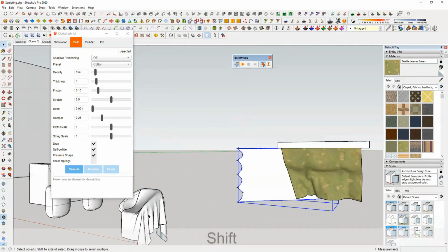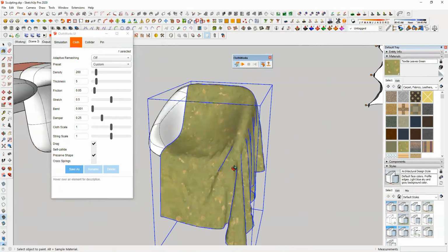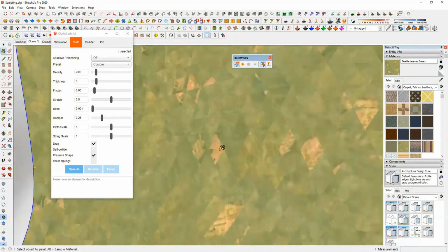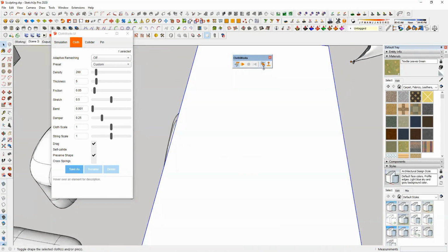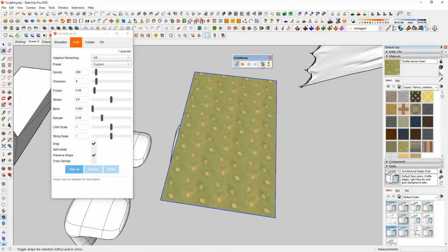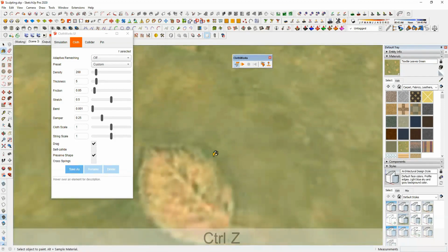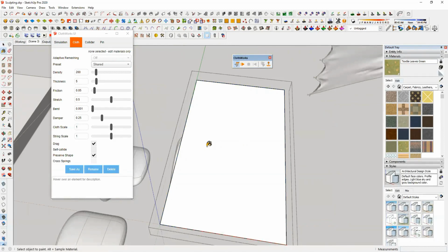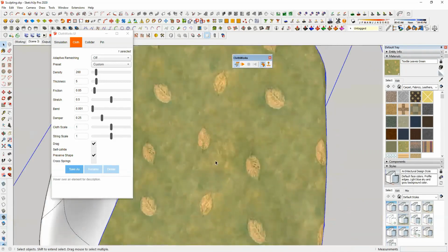Similarly, in this one, if I apply the material after the drape, then you may get some kind of unwanted results, as you can see. So the best thing is not to apply material like this. Unwrap this and apply the material and then wrap it. In that case, you will get better results, but you're not getting better results in there. So let's go and apply the material inside the face, and let's see if we now get the material. Yes, we got the material right this time.